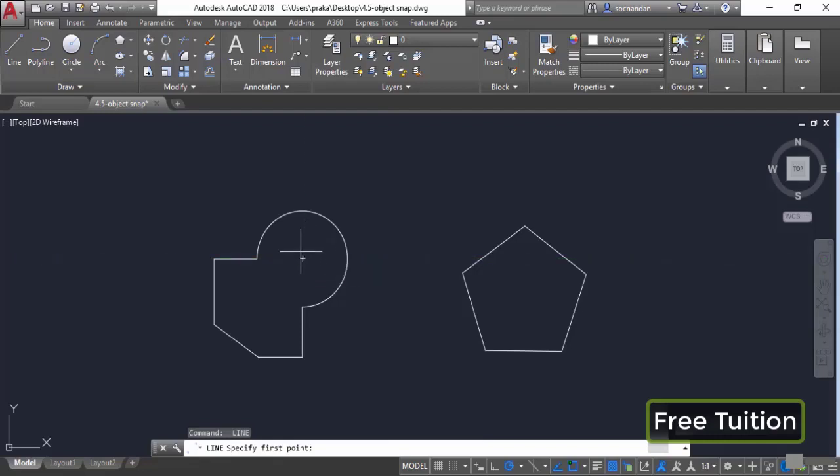You can click here, you can take the reference in vertical direction or in any other direction. So always make sure that Object Snap Tracking is on whenever you want to take reference of the object snaps, and you can turn it on by pressing the function F11 key on your keyboard as well. So let's move back to the drawing area and press the Escape key.